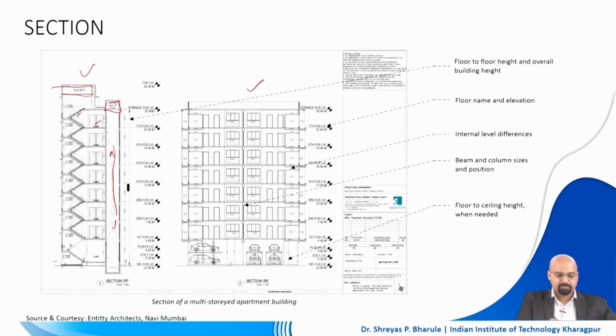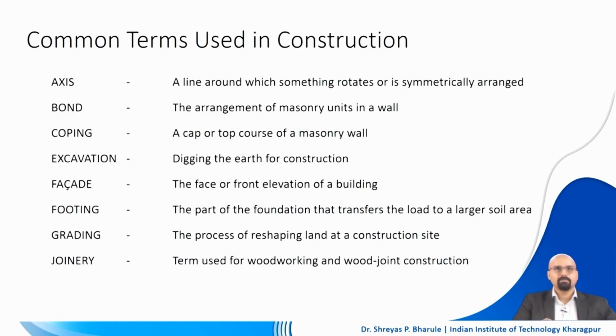So here as well you see the interior being exposed in a longitudinal section. So this typically is section RR, which is passing through the building longitudinally, and this is section PP, which exposes your staircase in a sectional view, right. So these are again to be mentioned in a section template, right.